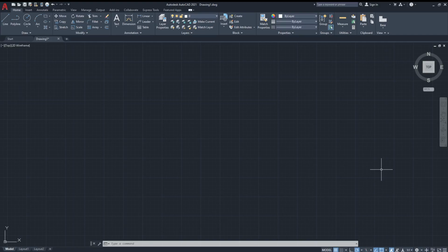Now moving on to how to draw a line. The first thing will be to specify the length of the line and the direction. By default, you should have this mode right here on the screen called polar tracking. This polar tracking helps you specify angles. If I go and click L, choose line, this polar tracking helps you specify the angles.